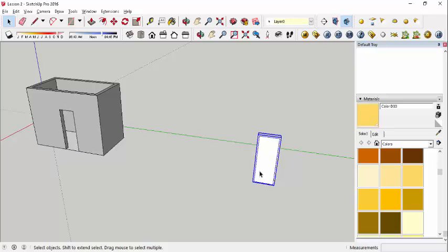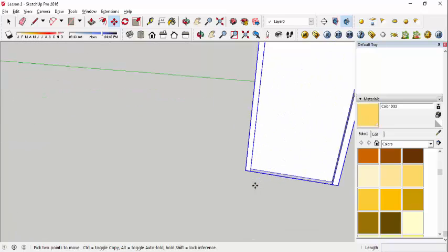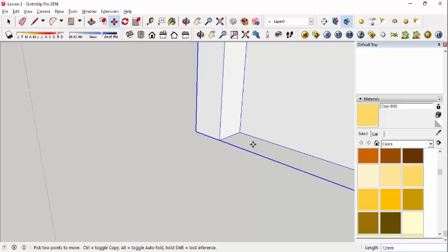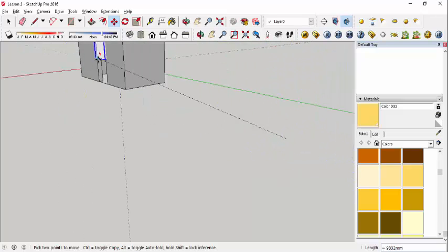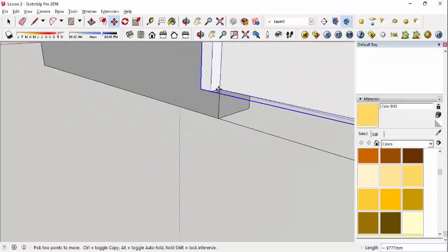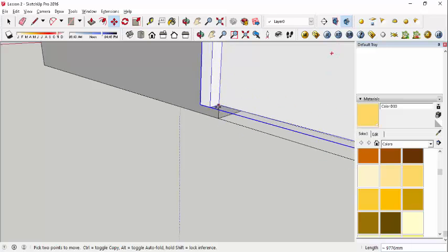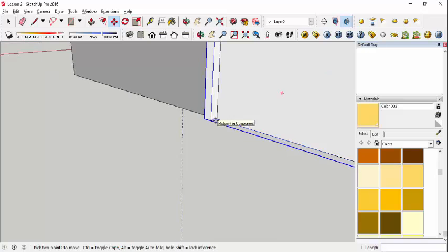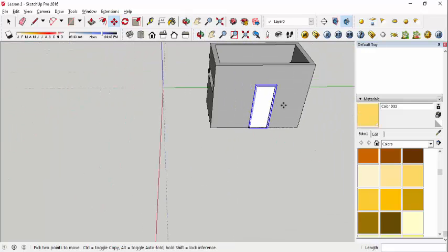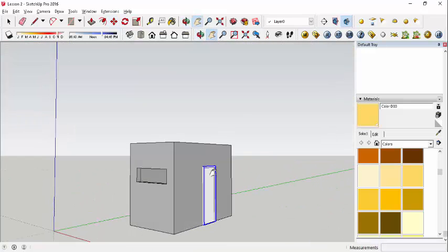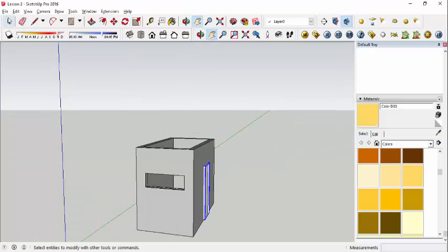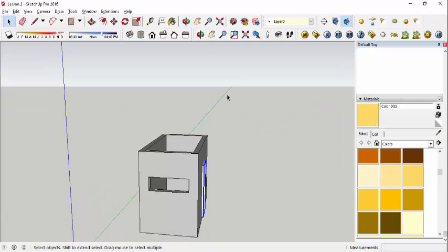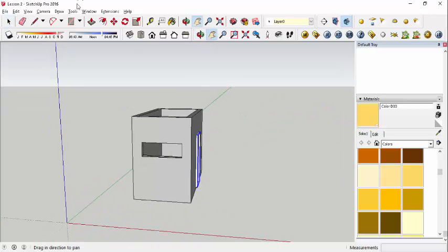So just click on M, and then I get this corner which is inside the jamb, and then click it here, snap it where the wall ends. Okay, there. Now you have a door. Next is window. Okay, so this is still in group. This is a component. Now let's do a window.